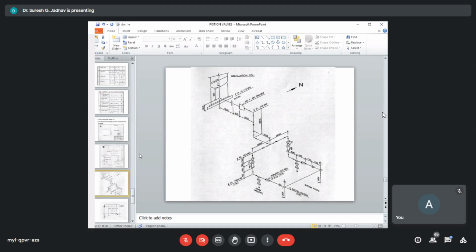So here we can use an H1 that we can mark on the reverse side of the drawing sheets. And next, utility sections are also established so that the most convenient utility header routing can be carried out. So this is all about how to start the piping GA.